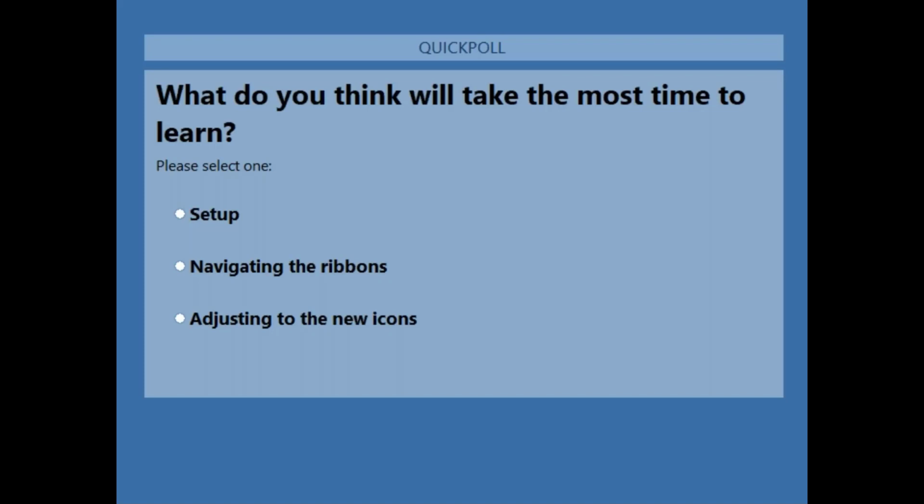Okay, I'm going to ask this next one too. Does the beam add command no longer automatically open up the beam dialog window? That's actually a setting. In the demo, I was using the quick add toolbar, which adds a toolbar along the top that only has your section size, your elevations, your connection types, and a couple of other options. It's meant to narrow down what you see while you're inputting beams and columns or bracing and streamline the process of getting those materials in. But it is just a setup in your user options if you want to turn that on or off.